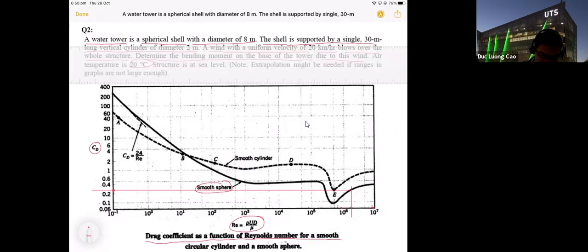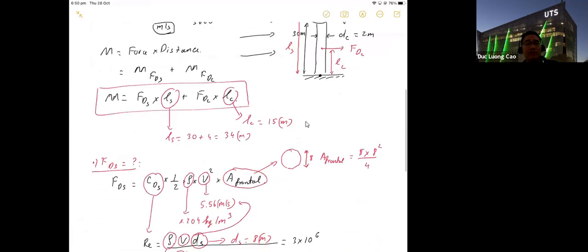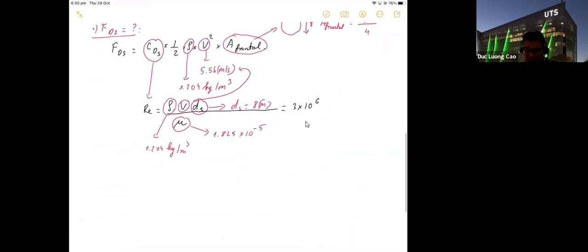And this one, I can see in the solution is 0.25, but in here I see around 0.27. I think this one is a half, 0.3 will be here, so a little bit below 0.3 is going to be 0.27. Actually 0.25 or 0.27 or 0.26, that's okay. The difference is smaller than 10%, which in fluid mechanics is accepted.